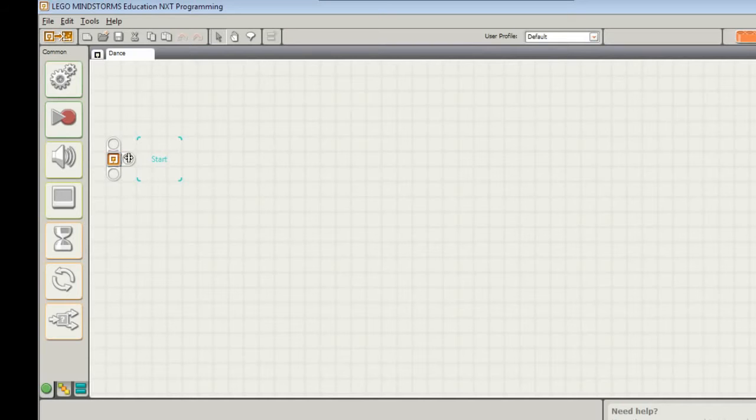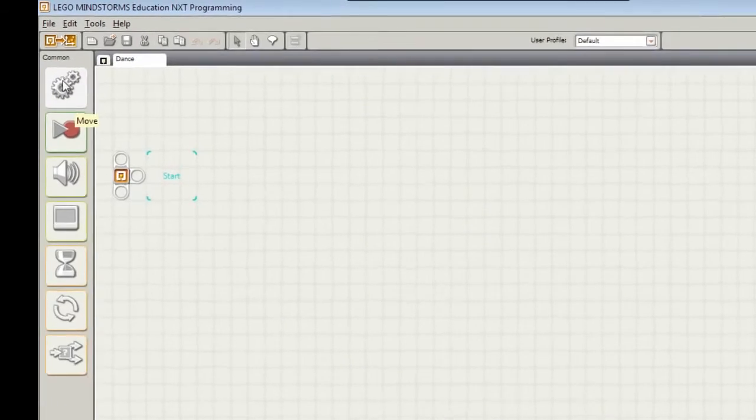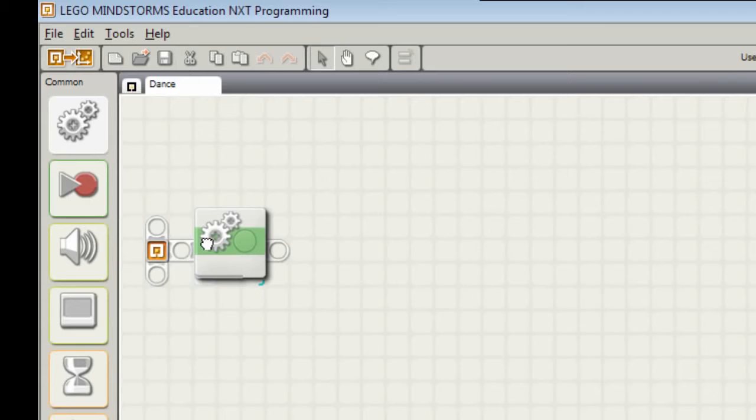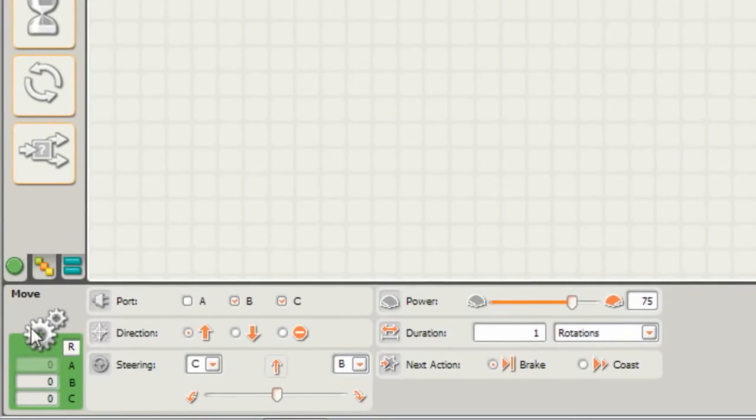You're going to be building up your program here on the screen, and we build it up by dragging out these blocks, positioning them on, and you'll notice that there was that little beam extended out. That's called the sequence beam, and there's a highlighted region there. When I let go of the mouse here, my block will actually drop into that highlighted area. You'll see that the block here is highlighted, and then down the bottom left hand corner of the screen we've got this area called the configuration panel, and that's where we can adjust the various settings for the selected block.